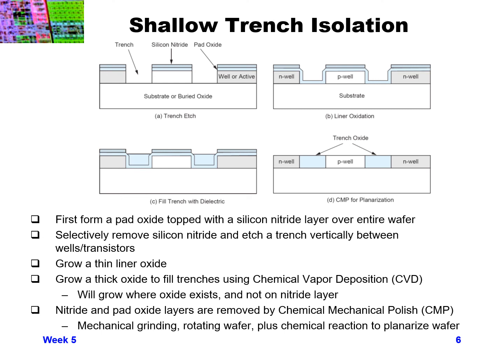So we get that thin layer of oxide. Liner oxidation is what it's called for that step B shown in the upper right of the figure. Now that oxide forms basically a seed layer for growing a thicker oxide to fill the trenches, and this is done using chemical vapor deposition.